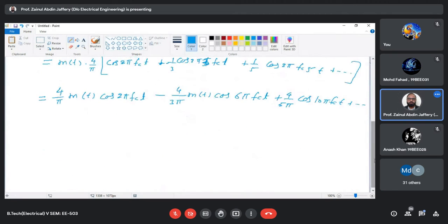So if you apply, क्योंकि हमें what we want is this signal only, इसको हमें कट करना है, ठीक है ना। तो इसकी फ्रीक्वेंसी कितना हो गया आपका जो है, ये आपका 3 FC हो गया, और ये 5 FC है, फिर आपका 7 FC and so on। तो you can simply put a band pass filter, so pass it to a band pass filter, right.